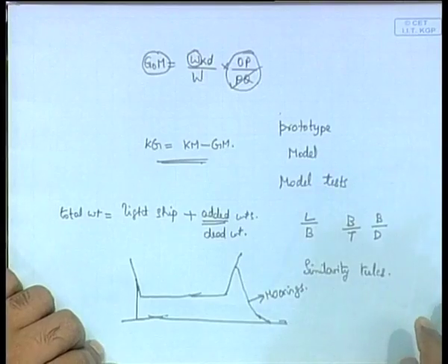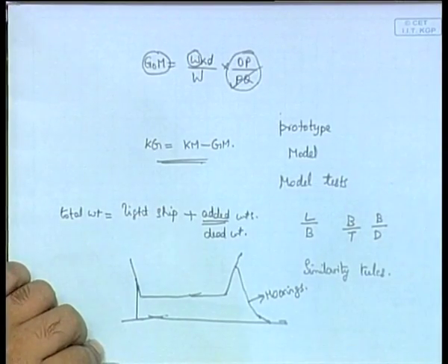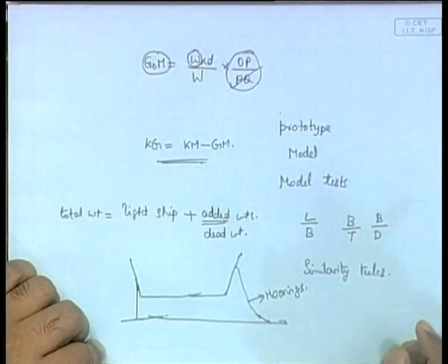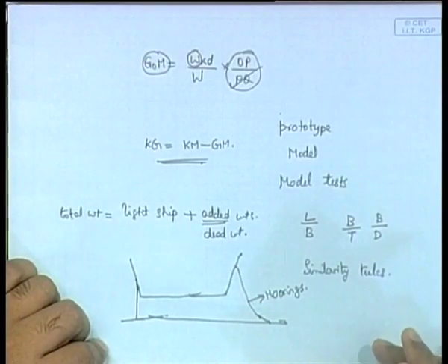So, this model is put in exactly still water, and then you hang the weight, you move this small weight, you see the inclining, you measure the distance through which the weight has moved, and you get GM. So this is an important condition: there should be no waves, which implies that there should be no wind and no current. Then these are the different points.